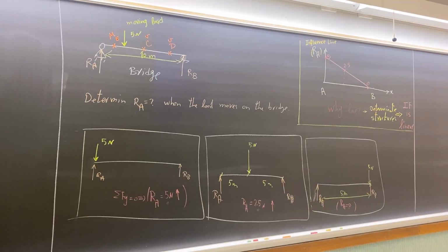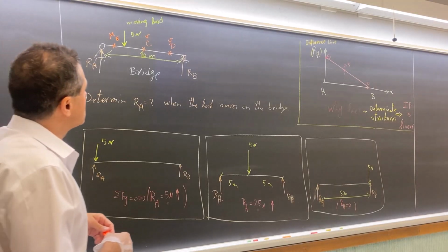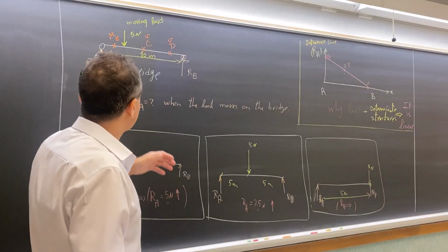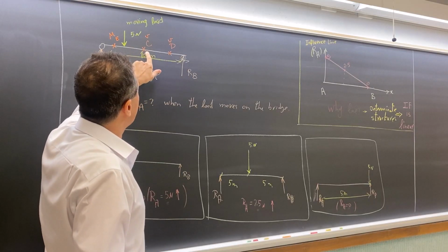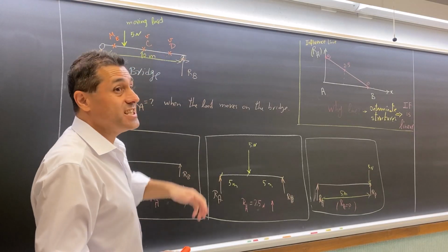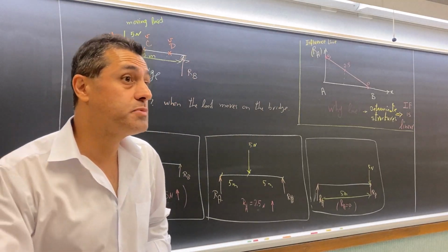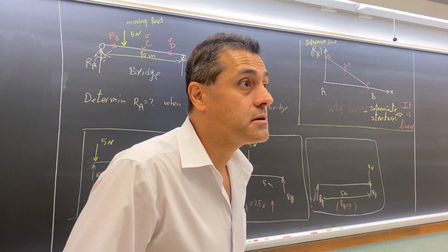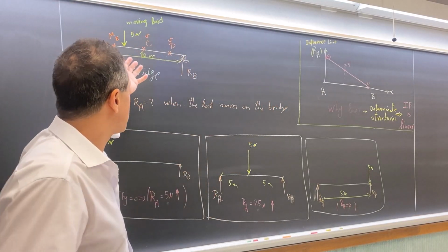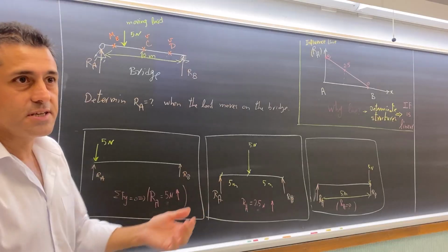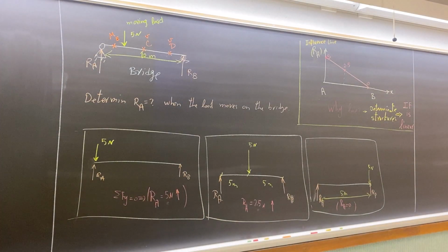As a designer, you want to go one step further. Which of the shear forces at points C, D, E, F, G, H is the maximum when Braden is walking on the bridge? That would be more complicated, because you cannot draw the inference line for all of them. So these are the concepts that we are looking for in this chapter.